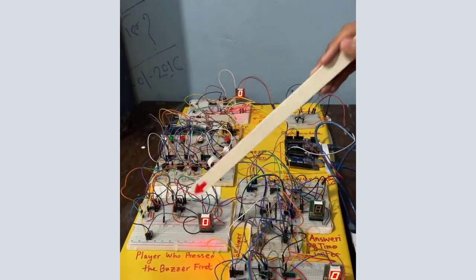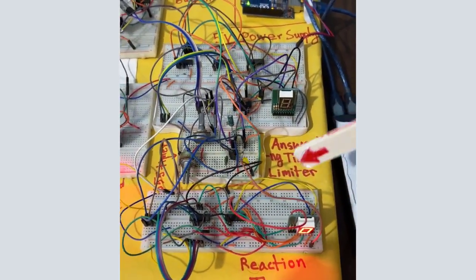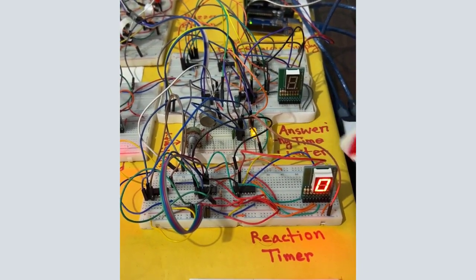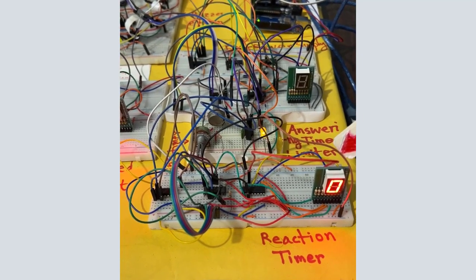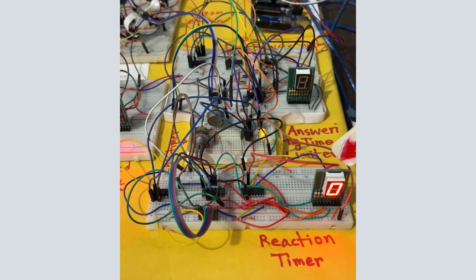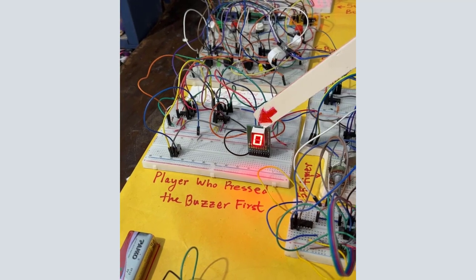Now there are 2 time counter circuits. One is the reaction timer, another is the answering time limiter. First we will go to the reaction timer block. After the host asks a quiz question, this timer will start to count the time up to 10 seconds. In the meantime, if any player presses the buzzer first, the display will be paused at that moment, and this is our reaction time. At the same time, this 7-segment display will show the number of the player who has pressed the buzzer first.